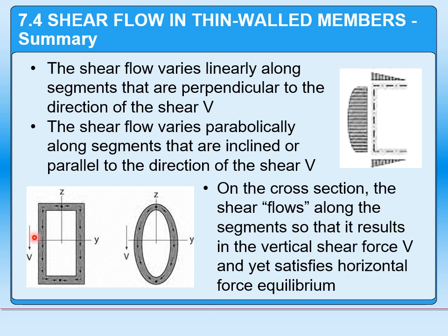So at the central neutral axis here, neutral axis here, that's where we're going to have our maximum stress value. Keep in mind, of course, we do have to look at stress relative to areas, so you can't just look at the neutral axis and expect the analysis to be good enough. Obviously, if you had different web thicknesses or different flange thicknesses, you'd have to analyze those.